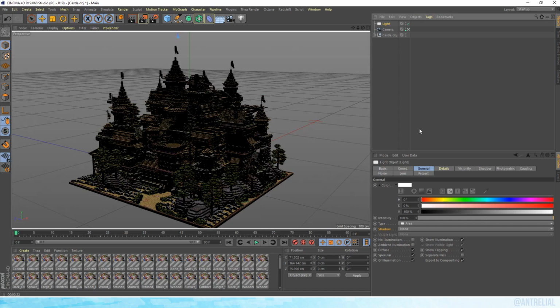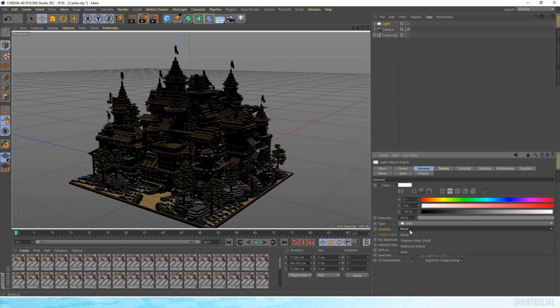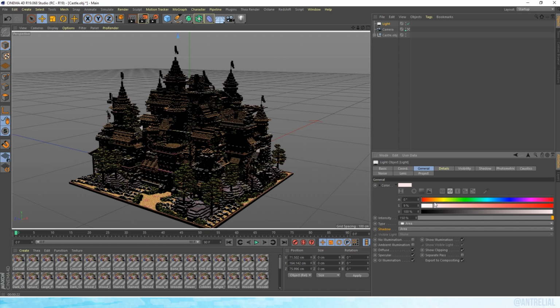This is because of a few things. First of all, you haven't selected a shadow type, so it's not giving actual shadows. Let's change this here. You click on the light, you go to shadow and area. Awesome. Next, the intensity of the light we said was very minimal. So we have to change this to, let's say, 150, and maybe give it a bit of a yellow tint. Something here, yellow-orange. Not too much, because otherwise it doesn't look great. The last thing is that the shadows were too dark. This is because of global illumination, and let's not get into the details, but basically it doesn't have anything to reflect off, so we need to give it something around the build so it can reflect off.